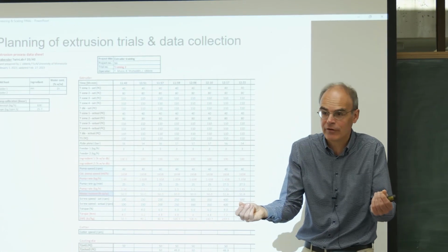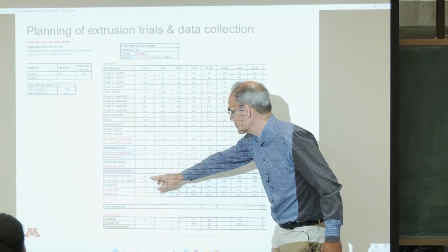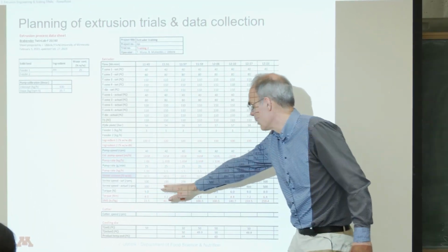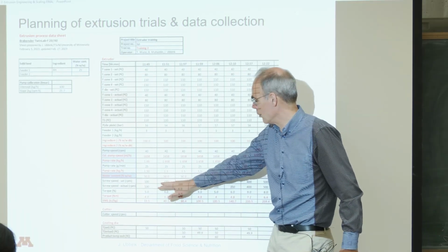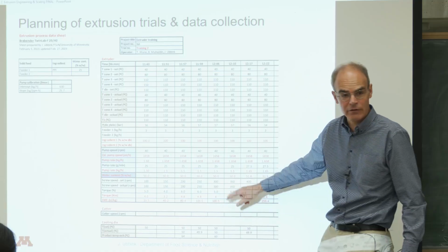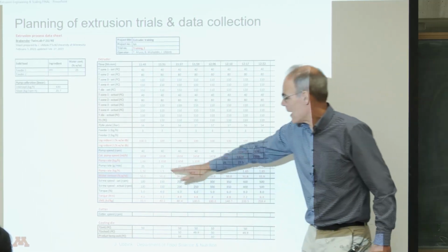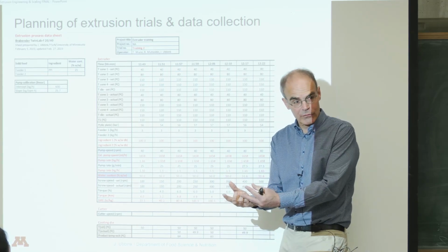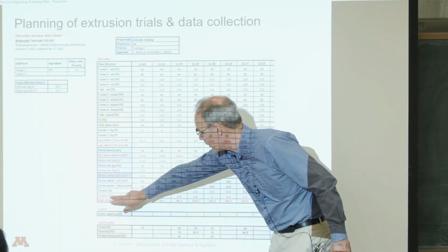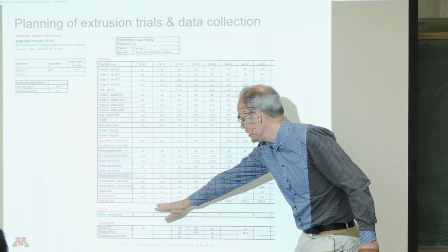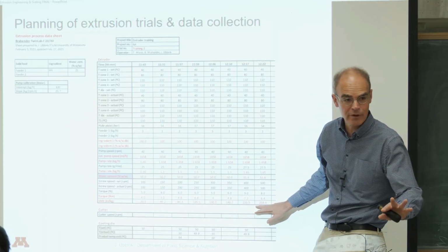Is that water content still 50%? These types of things. And then what we varied in this series, finally at the bottom here, is a screw speed sweep, as I call it. We start with 100 RPM, and go to 150, 200, 250, 300. So we vary this one parameter, which is screw speed, and then have a look. We collect the products, and we can also calculate some further parameters, the torque and the SME. We see variation specifically of that specific mechanical energy. I will come to that parameter.